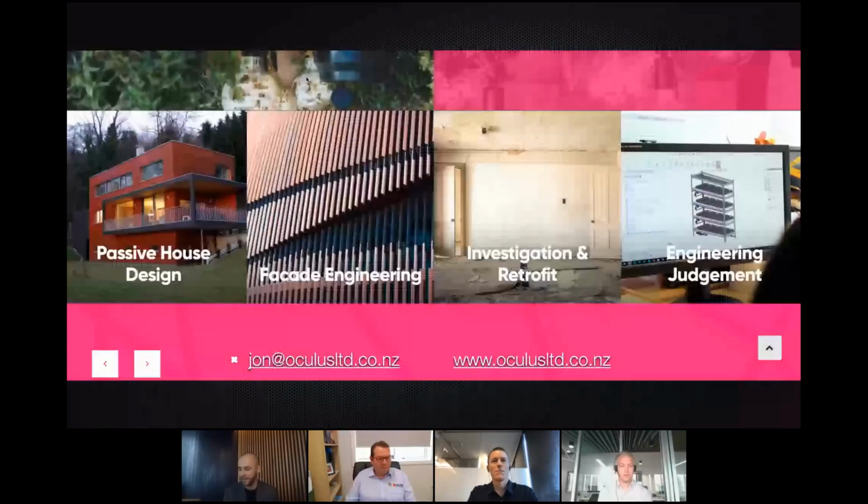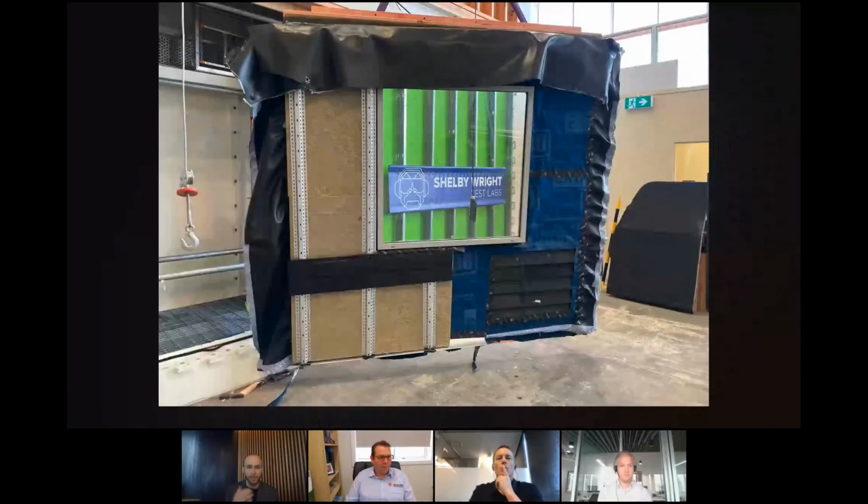Awesome. Thank you so much, John. I've got a real quick question. It's the approach of cladding over the face of that existing facade. It makes a lot of sense, because often when you pull the facade off, you get into that cavity, and there can be all kinds of issues. But if you're cladding over the face, do you replace the windows so that they sit in line with the new cladding? Yeah, so that's a replacement window in that image there.